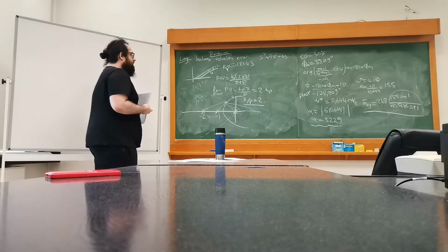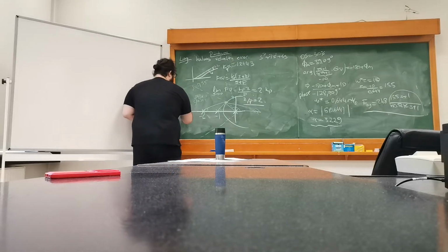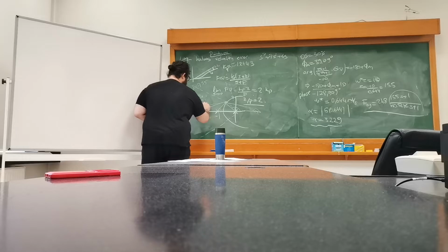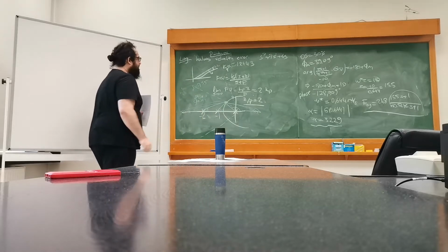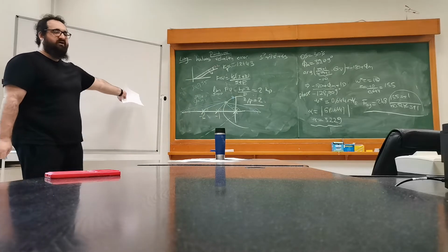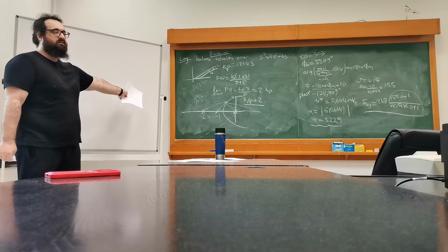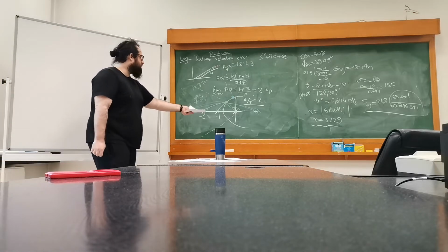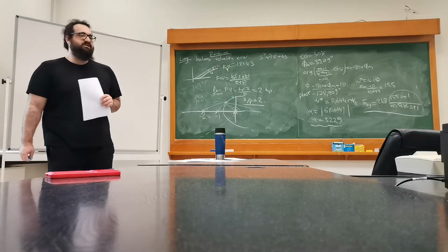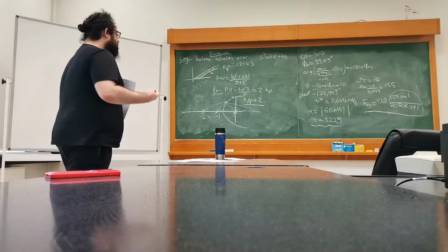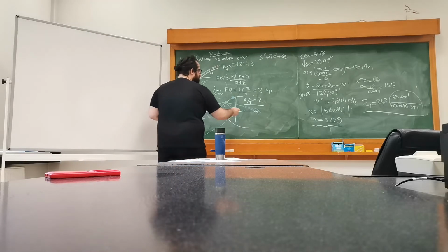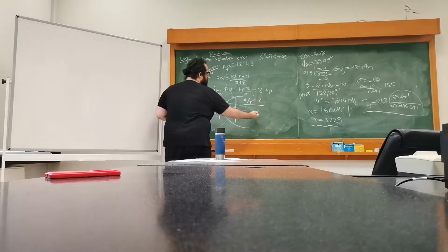And, well, if it's here, let's have it here, the angle contribution might not be, again, that relevant, but since it's far away, it doesn't really have that effect. So it's not really affecting the system because it's out of the dominant region. So if you want to design a lag controller, we still want to have this angle condition here.